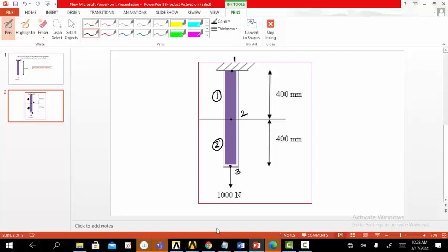We have to define these nodal points in ANSYS APDL with the aid of exact Cartesian coordinate positions. The nodal position 1 can be taken as the reference. So the nodal coordinate position in Cartesian coordinates for the first point is assumed to be 0, 0, 0, the origin.